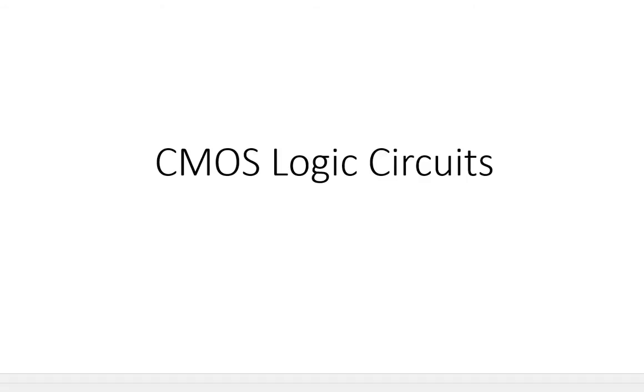Why the name metal is given? The gate of the transistor was made of aluminum metal in the early days. Now it is made of polysilicon. As oxide is considered, silicon dioxide is the material between gate and channel. As semiconductor is considered, silicon is the semiconductor material used, and it is a group 4 element in the periodic chart.